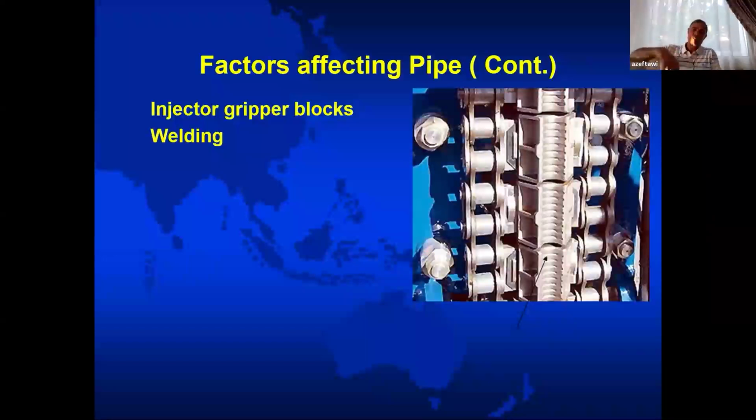Then we spool it on a big spooler. And then we bring the end of the first spool to the beginning of the second strip to spool. And then we weld them together, but we cut at 45 degrees and we weld them together in a process we call strip bias weld. There is no filler material. And then we keep doing that till we have the total length of pipe as a strip.